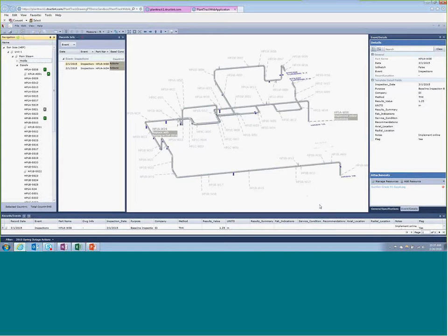One thing that's also really powerful, and I'll get back to this on the dashboard when I close this interactive demo, is the fact that you can set notifications. With this particular monitoring application, notifications can be sent upon a particular damage threshold that you, as the engineer, as the owner, want to set. So for example, if you say, I want to be notified every time I get 10% accumulated damage, I want an email sent to me.